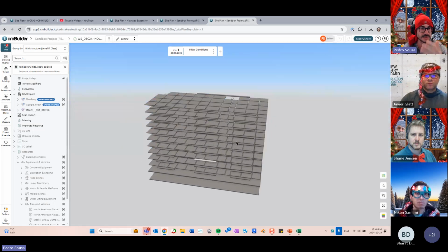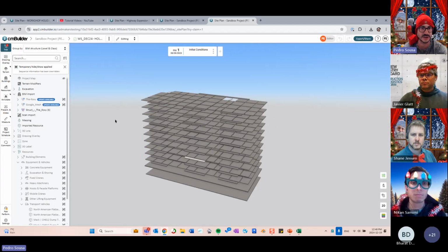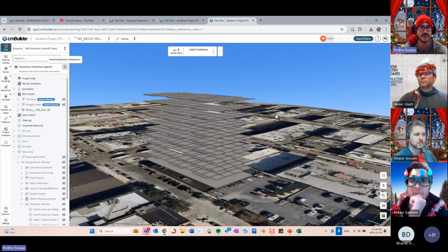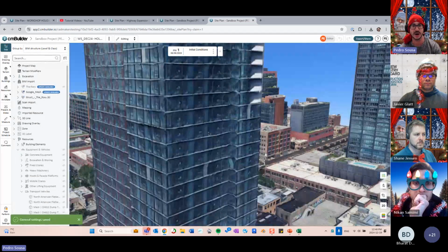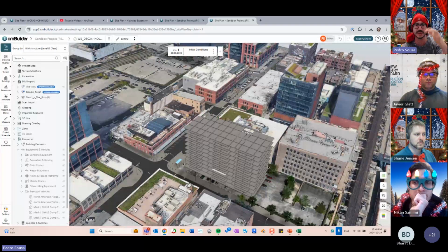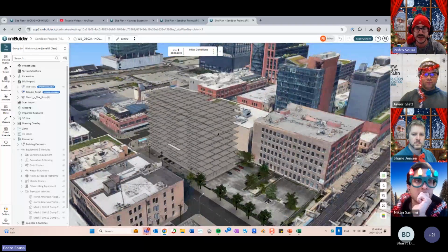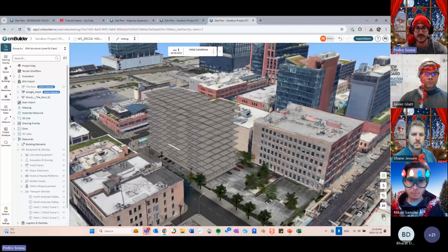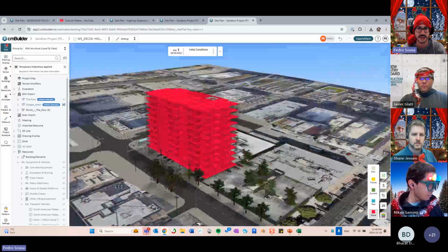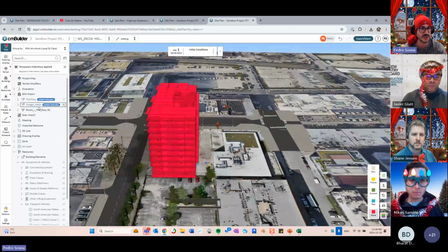So sometimes it's very easy to understand those changes, right? When you bring in a new model, you can see right away what is new. But if you're working with all your scenario turned on and a bunch of parts in here, and you're trying to understand what the new parts are and you cannot visualize them very well because they are smaller than the slabs or whatever, you can simply click on the sequencing view, and in the sequencing view it will highlight all the parts that are new and unsequenced in red.